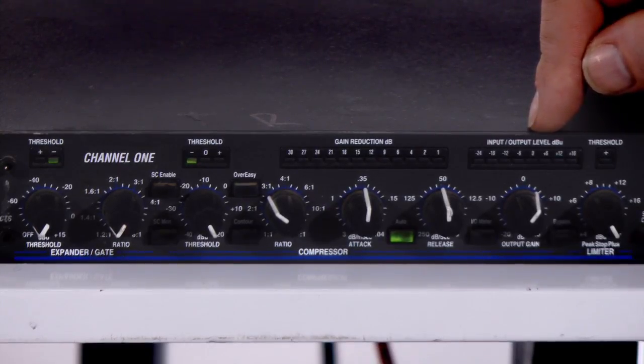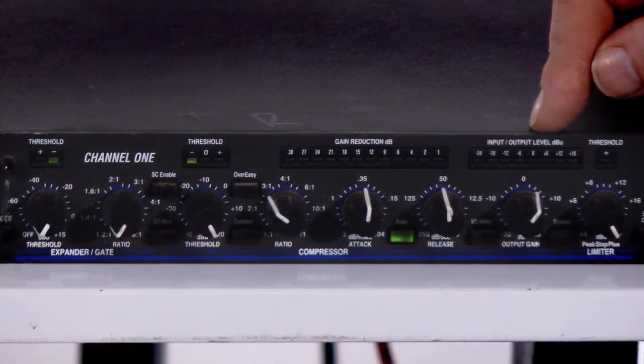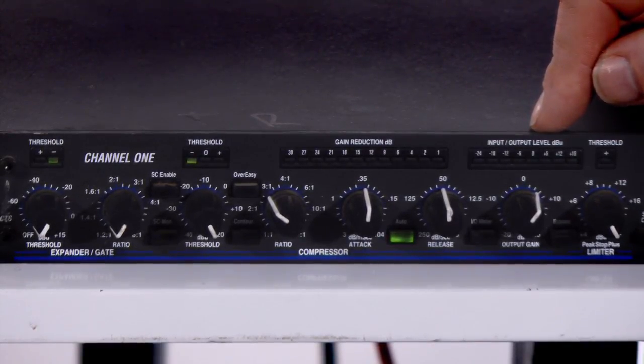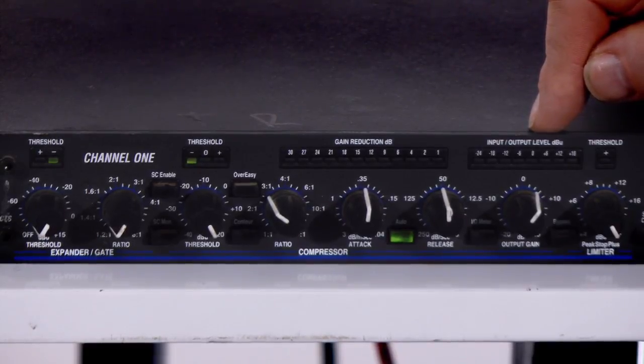The final control that we need to worry about is the gain makeup control, or the output control. Compressors are going to work by generating gain reduction, a reduction in gain. And so to make up for this gain, the final stage of a compressor gives us the opportunity to return that gain back to the signal path so that we are maintaining gain structure.